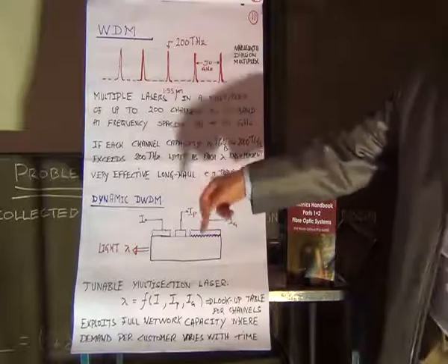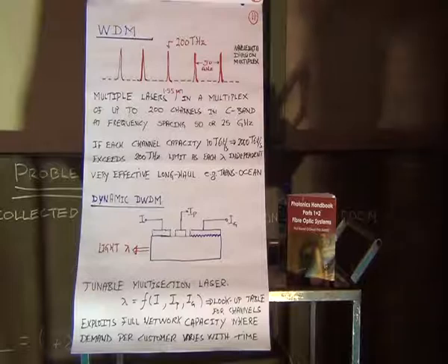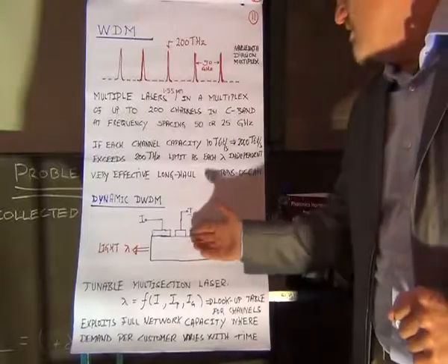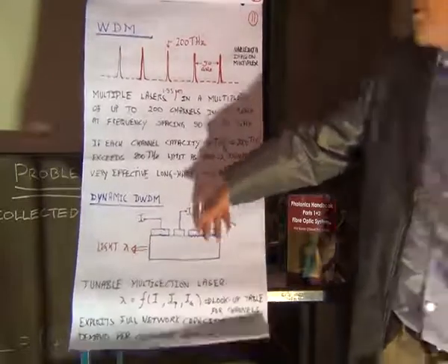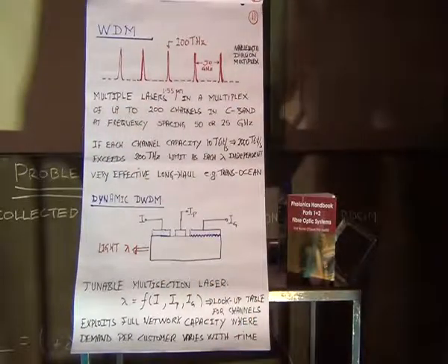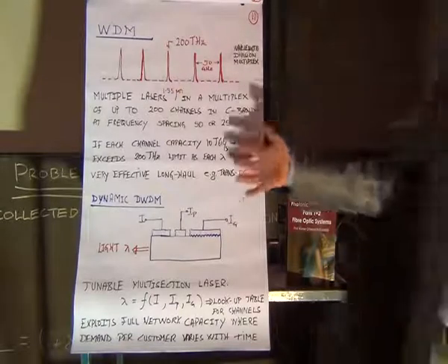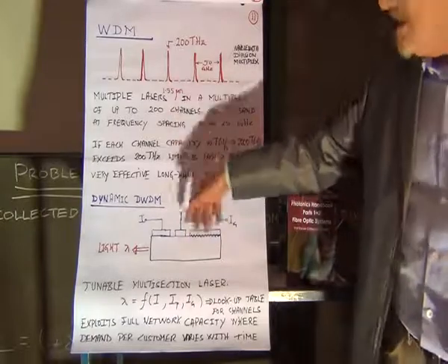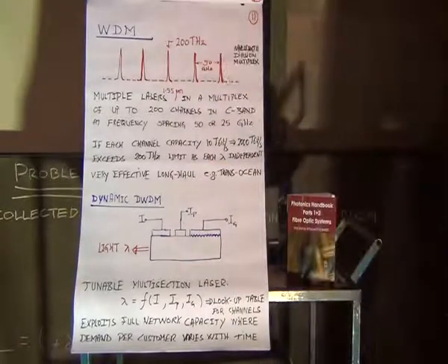And when you inject current into that grating, you flood the grating with carriers, and there is an effect on the refractive index of the grating. Okay? And that changes the reflected wavelength. So we have the possibility here to electronically control the output wavelength rather than simply band gap engineering. You do band gap engineering to start with to get your center channel. And after that, you would flood the sections of the laser with carriers, slightly change the refractive index, and tune the laser to one of the other colours, 50 gigahertz apart.